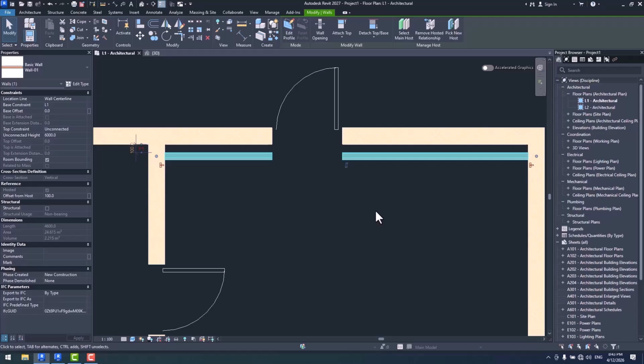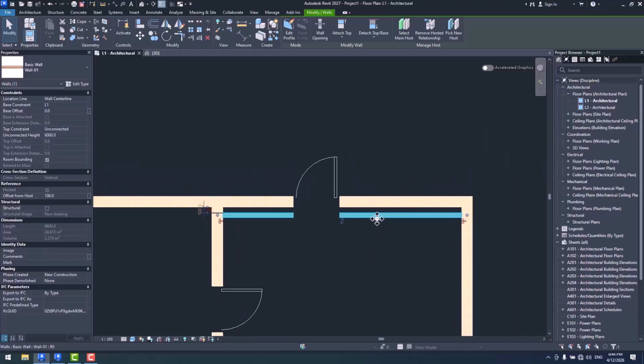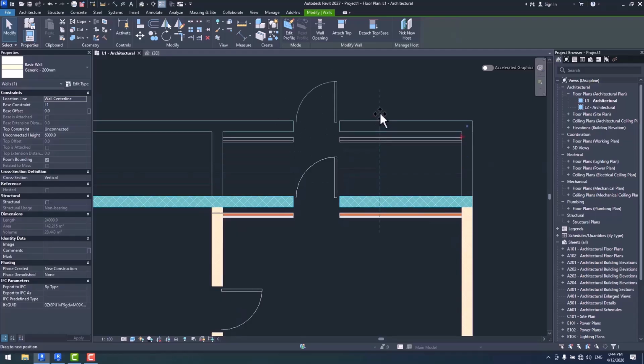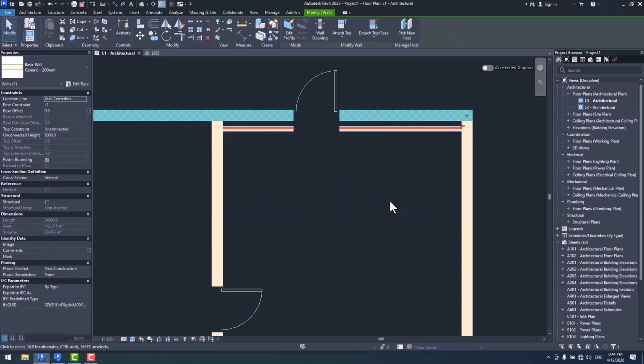This is a very useful technique when dealing with two-layered walls, guys. We would be able to set the secondary wall or layer as a hosted wall with auto join activated. And this way, we would make sure that the openings would be added to the whole thing correctly later on, but also we won't be facing any difficulties or problems in case we needed to apply further modifications on the walls. And by the way, guys, I don't know if you have realized this or not, Revit is still supporting the whole technique for setting the finishing layer separately.